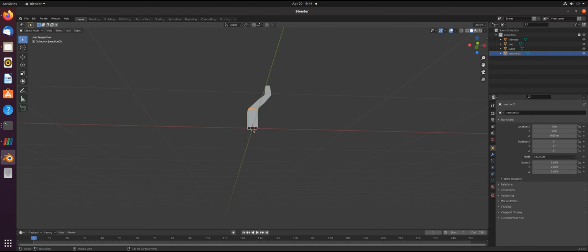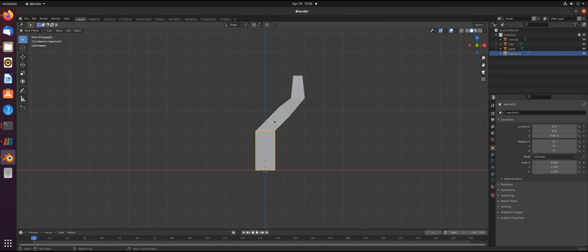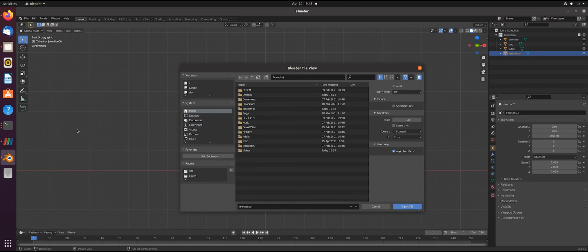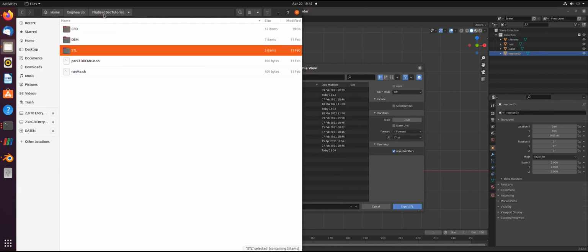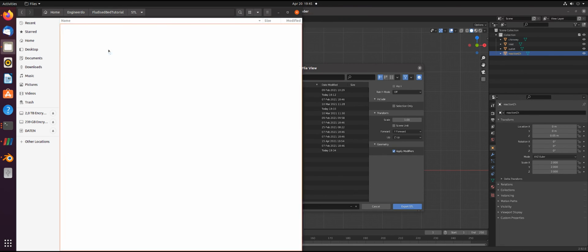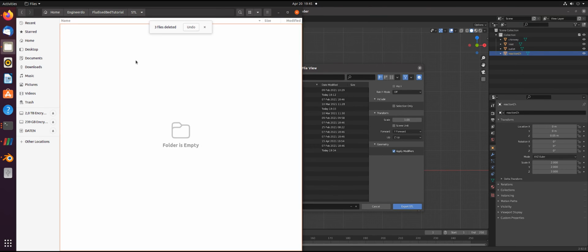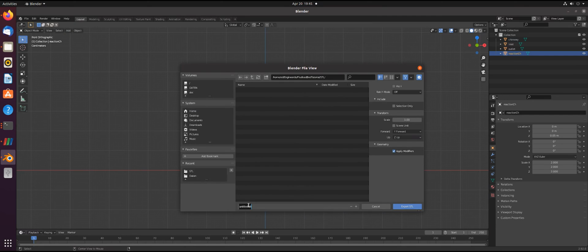The flow enters through the inlet, streams through the reaction chamber and out of the chimney to the outlet. Now I will export the files by File, Export, STL. The files shall be exported to the STL folder in the main directory of our case, because we need them in the DEM and the CFD simulation as well. To select the path, I go into that folder. Since I don't need the original files anymore, I get rid of them. With Ctrl L, I select the path of the folder. I copy the path into the path field of the export window of Blender.